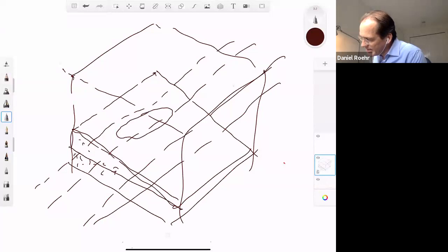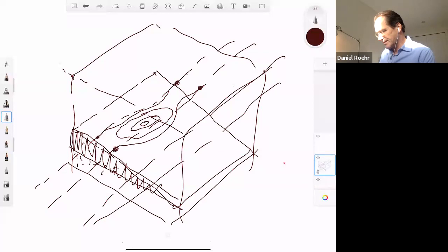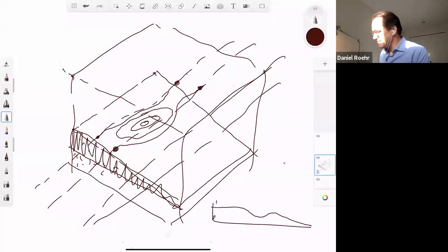And then you could go in and say, okay, I will design the contours, the new ones around. And then this one maybe goes to enhance this form. And then here's a contour inside to show the depth. So immediately it helps you to visualize the grading very quickly. And because this is at a slope, it gives you the understanding, this is actually going downhill. And then you can also think how that little swale system would look in section. You can see I just drew it roughly, but this would be the area here. So it gives you a really good tool.